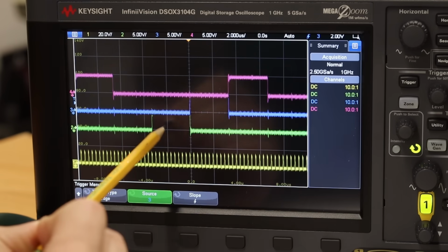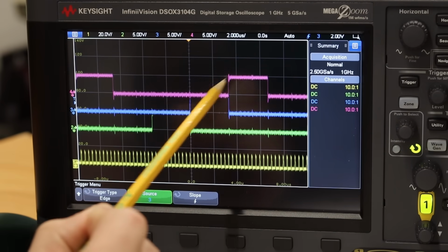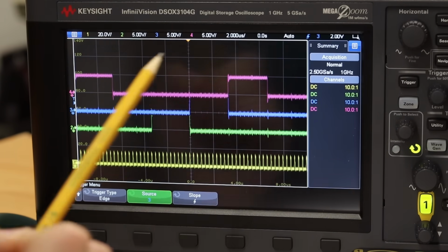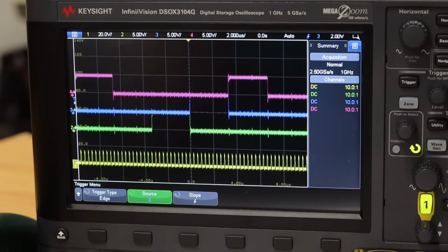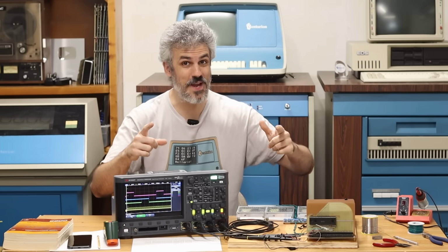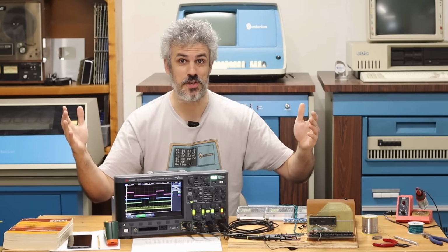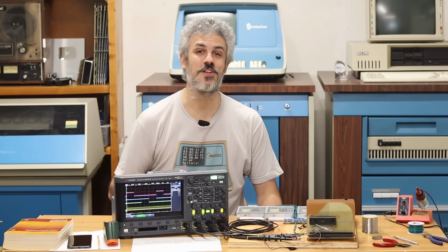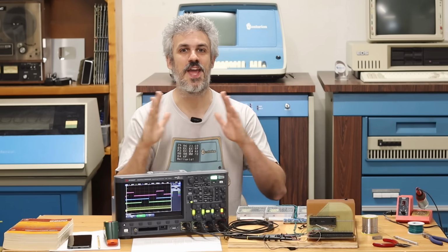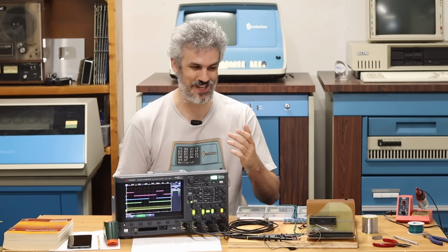Yes! Check that out. That's exactly what we wanted to see. We can see that each address goes high and then low sequentially, and they never overlap. The CPU is executing jumps to the correct locations, and it's doing it perfectly. We are running real deal code on our Homebrew. Here we are chugging along at 3 megahertz executing code. It is doing unconditional jumps to specific locations in memory on a tight repeat.